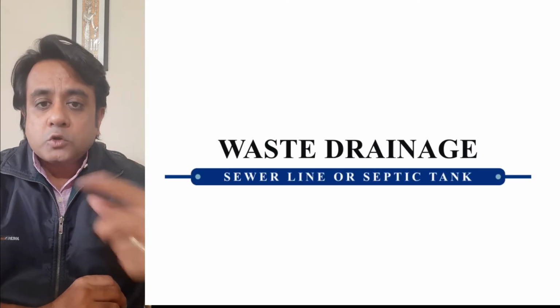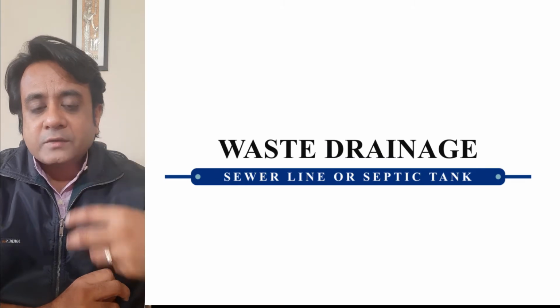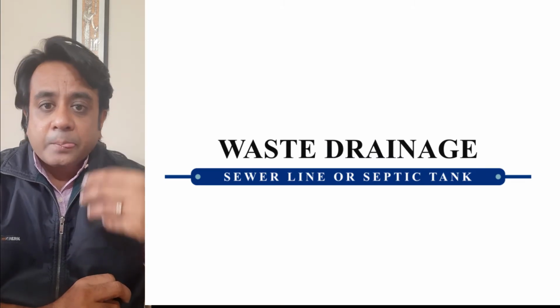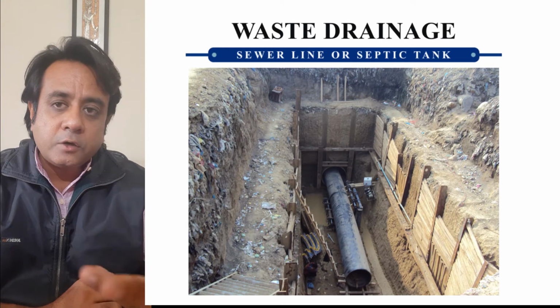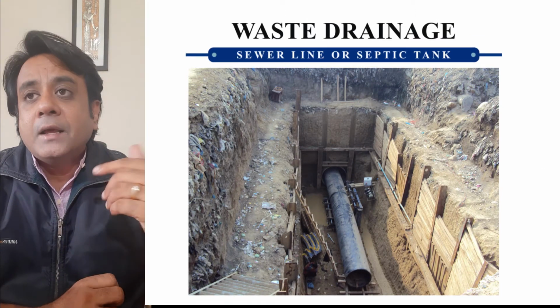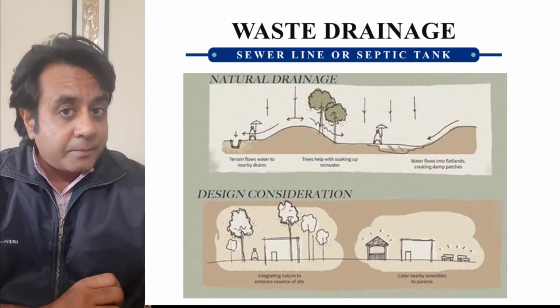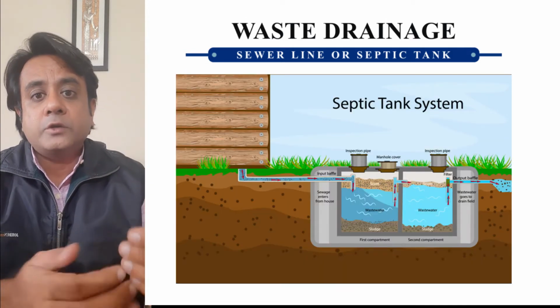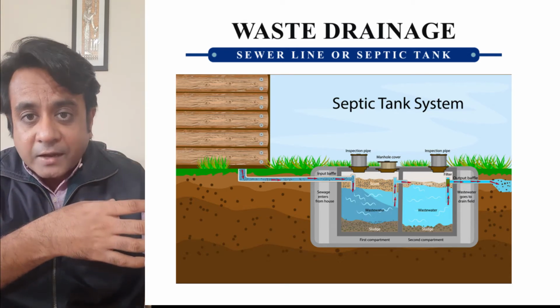Now with that, you also need to understand the outlet of this water. Once you consume this water, wastewater is produced. This needs to go out. If there is a government sewer, then of course most of the time it is connected to the government sewer and goes out with that. But in case that is not available, you'll have to make a septic tank. When you do a septic tank, it shouldn't be very close to the well. Maybe you have some other site constraints.